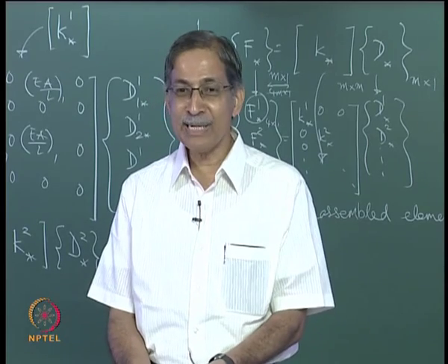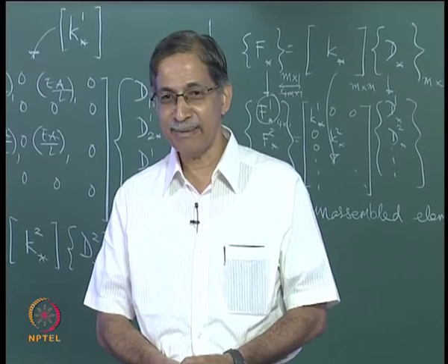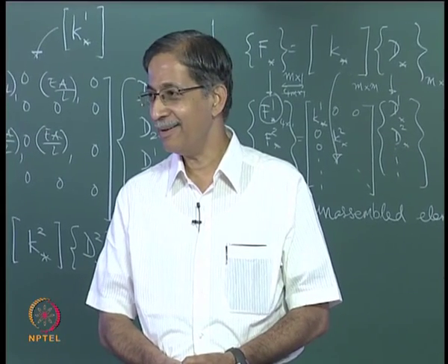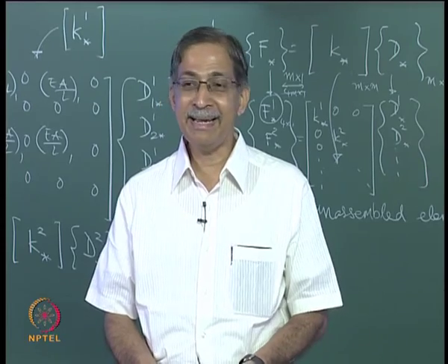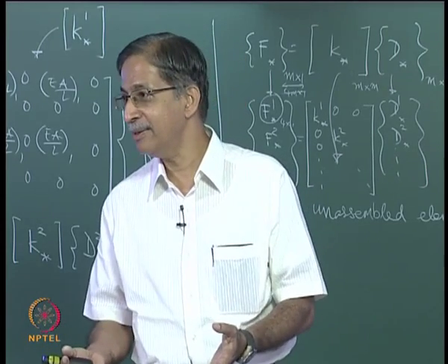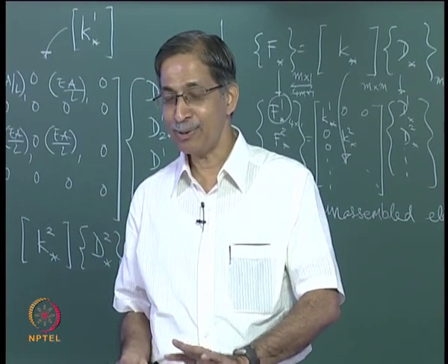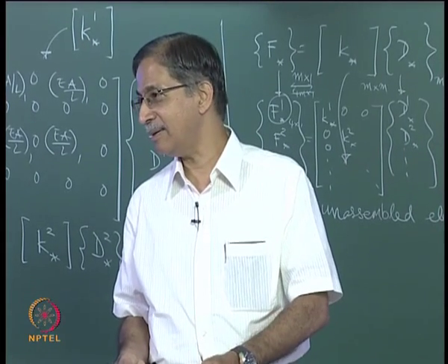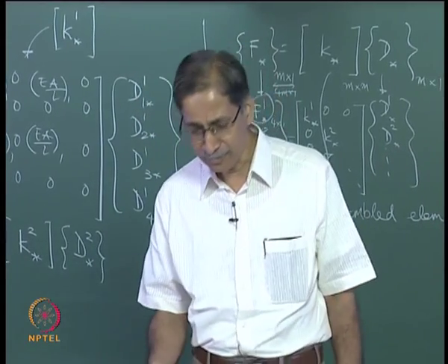So you don't get any unique results. These are unstable structures the way we have drawn them, right? That is the simple reason. You have rigid body movements, so you have independent displacement vectors, which is fine, but you do not have independent force components in the force vector. That is a simple answer, but there is more to it.